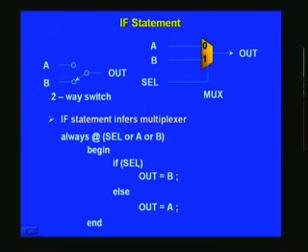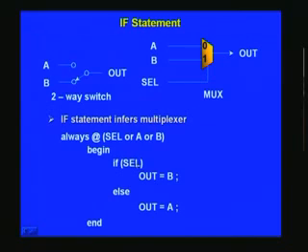If select is, if you don't put equal to 1, which you can also do, it implies that it is 1. So that's a short notation, but I personally discourage this. You put double equal to, then 1'b1. That will convey how many bits, and all at one stroke. As we said before, it should be as much self-documenting as possible, so as to minimize your comments, which need to be at the bare minimum, and explain the modules rather than every statement that you have written. Right?